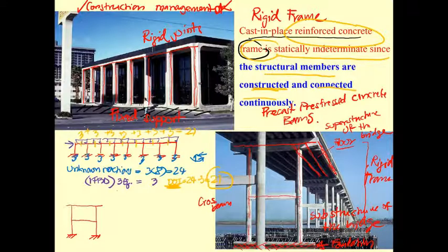The substructure has two stories. By using the same method as before, on the top you may just cut the frame. When you cut the frame, each cut is going to produce 3 and 3. So this is going to have a degree of indeterminacy of 6, as you know before. If you don't want to, you may use the classical procedure. This also has 3, this also has 3. So your frame is going to have one of this and another one of this.